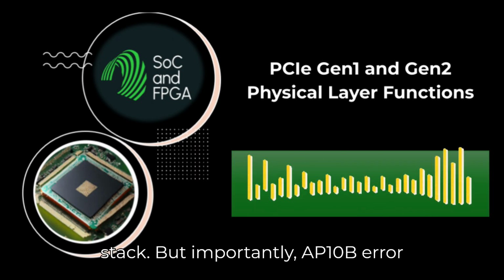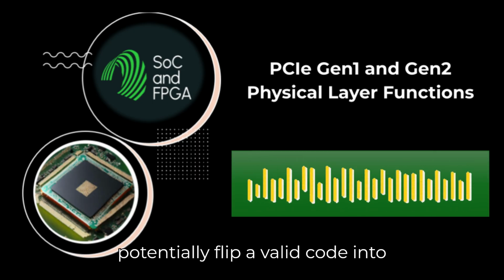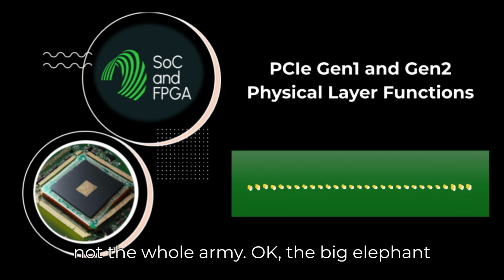But importantly, 8B10B error detection isn't perfect. Two errors could potentially flip a valid code into another valid one. That's why you still need stronger checks like CRCs at the data link layer. First line of defense, not the whole army.